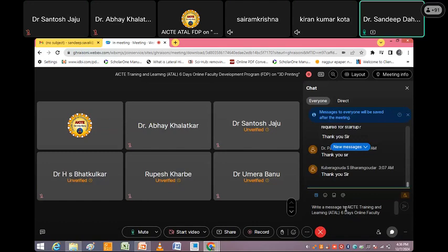If the file size is very low, in some cases you may import the STL file in ANSYS and perform the analysis directly. But in many cases, you have to convert the STL file into an ANSYS compatible file like an IGS file or CATIA file, so that ANSYS can import it and you may perform the analysis.